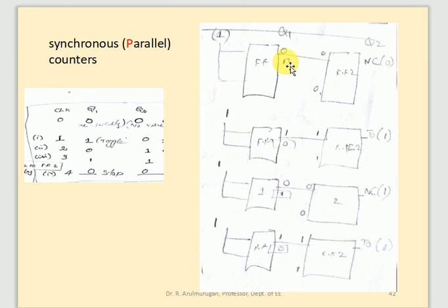Okay, fine, good. Next one I have written for reference purpose. Then now you can apply that one, again toggle. Toggle means 1 is shifted into the 0. The 0 I am going to keep here for my reference purpose. Then 1, 1, okay, again clock also 1. So toggle. So 0 is shifted into the 1. The 1 I have written for my reference. And again 1 is input and clock also 1, input toggle. This 1 is replaced into the 0. That's all. That's why you are going to write it like this.